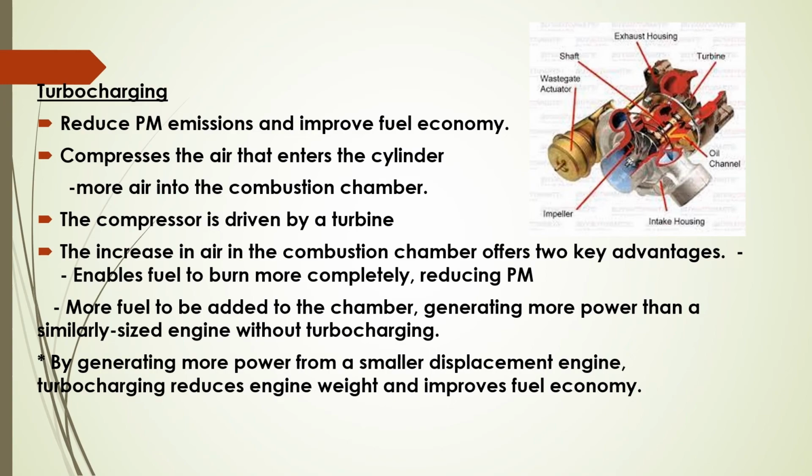The increase in air in the combustion chamber will offer two key advantages, which enables fuel to burn more completely and hence reducing the PM. Not only that, more fuel can be added to the chamber, generating more power than a similarly sized engine without a turbocharger.